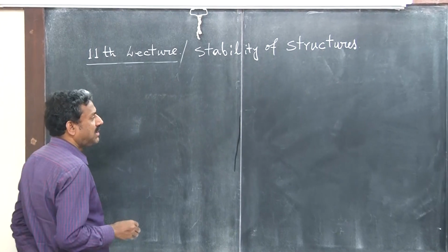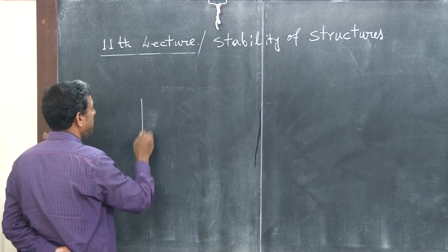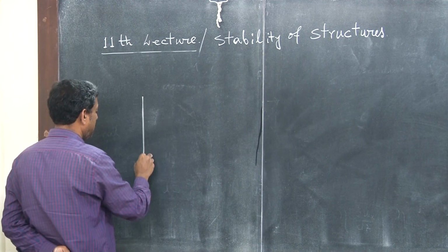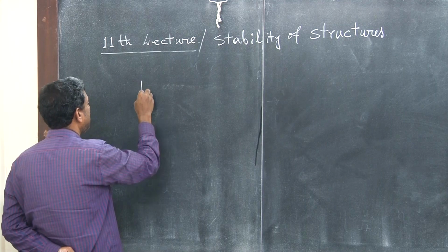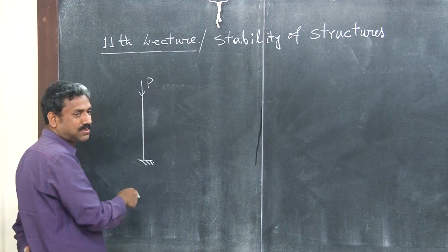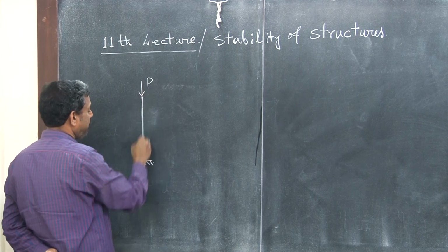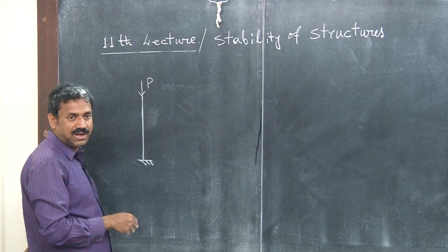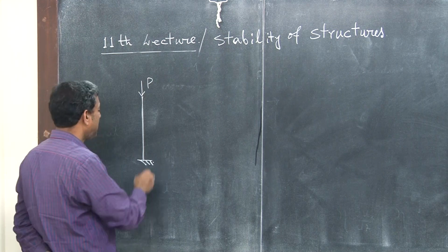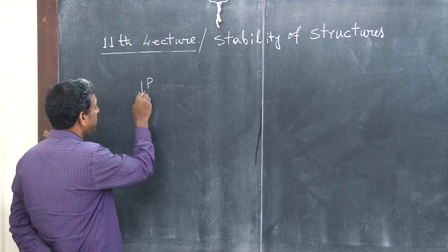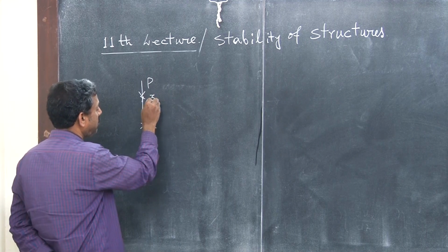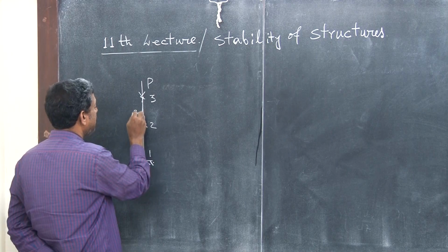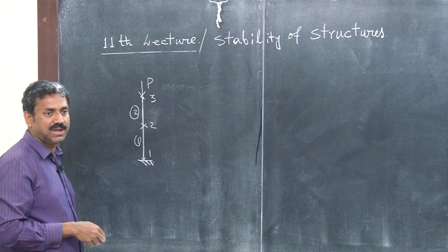So you have learned that in matrix method or finite element, for example, there is this column. Okay, right. So we want to find out the buckling load P for this. We know the closed form solution for that. Either we can discretize it into finite elements, right, or in matrix form, right. So we know how to. So we can discretize using beam column elements. These are defined as nodes 1, 2, 3, and these are defined as elements, right. And we have this nodal connectivity, right.